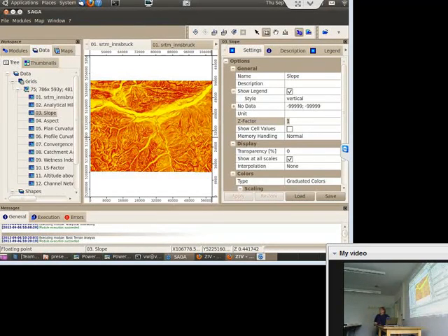So the simplest way is to use the grid calculator and multiply the grid with this factor. Then the actual values in the grid will be in degree too. But almost all modules that are working with such grids, like slope and aspect, expect it in radians. So SAGA just uses this factor for converting it to degree.